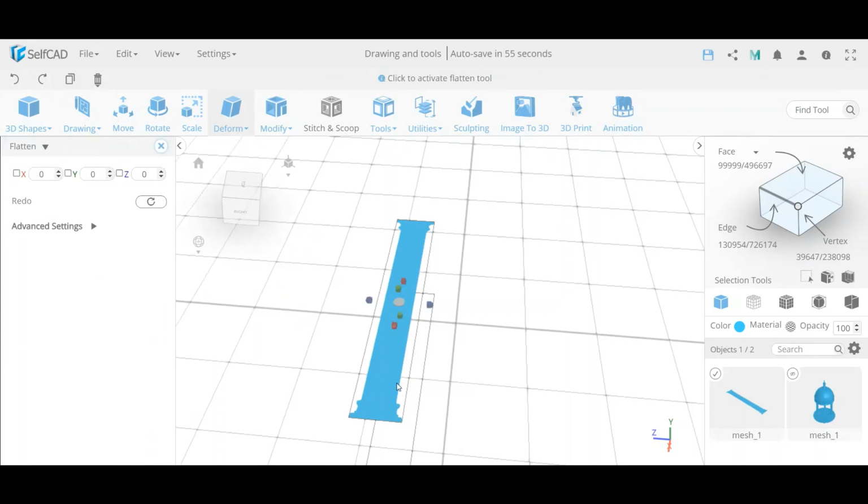I know the radius of this, I calculated and measured that, it is 30. But that means I need to move it in one direction to flatten that again. I need to slice it in half, move it by 15. But the problem here is that if I use the text boxes, those are always symmetrical, meaning it will move half of the 15 from one side and half from the other side, and I need to keep one side intact. So how do I do that? I can start moving the gizmos, manually drag them, and start seeing what's happening, but it's quite difficult to get a number. You see, I'm looking at how it goes.